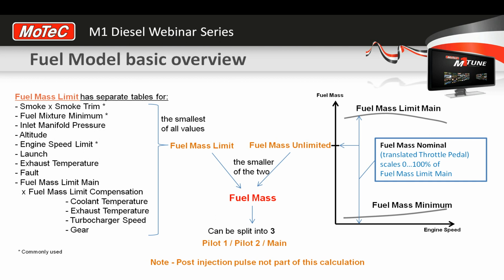If the engine's set up and running okay mechanically, and you've got your ref sync mode and your injectors set up right, so the injectors are being driven correctly, then the fuel tuning can be as simple as just those three tables and you're on your way. It's not like a petrol where you have to get the air fuel ratio at one particular level.